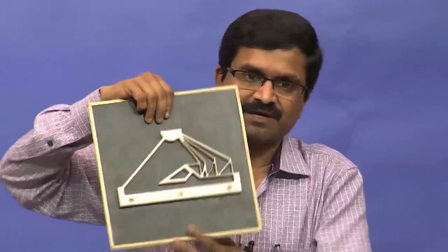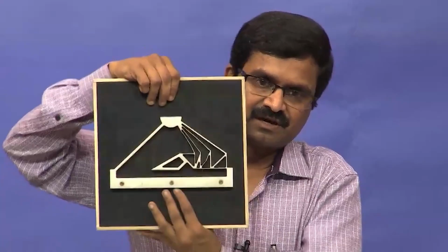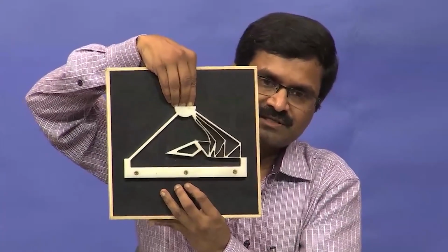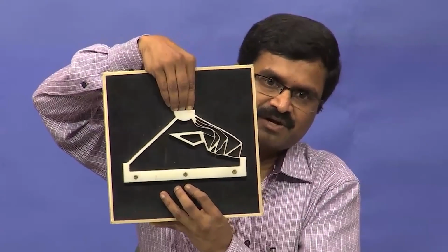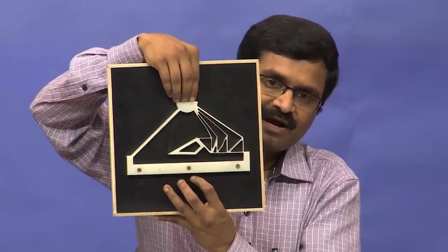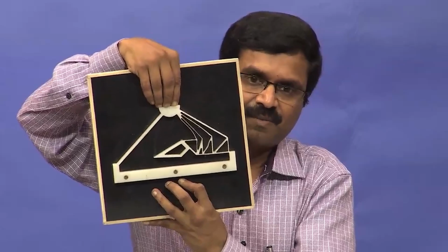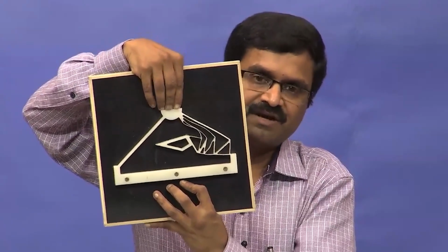Okay. And here is another device. This is also a displacement amplifying compliant mechanism, which is fixed over here. This entire piece is fixed, screwed onto this board. When I apply force downwards, this moves upwards by a large amount, right. When you hold it in your hand, you would feel that there is large displacement and large rotation, but very little strain, and even if you do it a billion times, this device is not likely to fail.